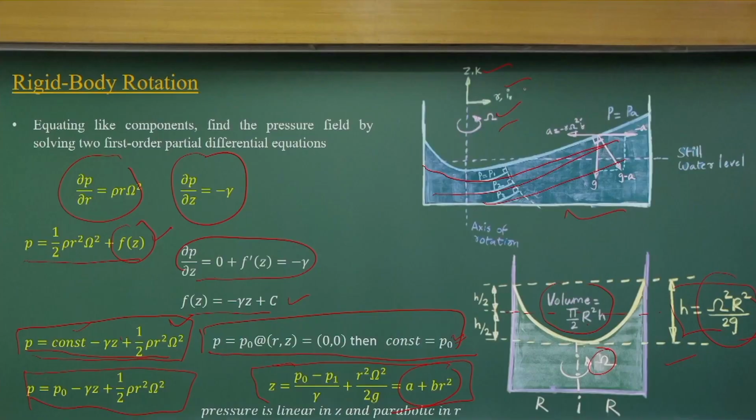But in real life problems, like a fuel tank in a rocket that is moving with different accelerations, what could the fuel tank pressure diagrams be, and what would the conditions of the fuel tank be because of the pressure exerted? Those need to be studied. That is the reason to look at it in vectorial form to solve these problems, where we just have to remember that the gradient of pressure is equal to the density times the vectorial difference between the acceleration due to gravity and the centripetal acceleration component because of uniform rotation.